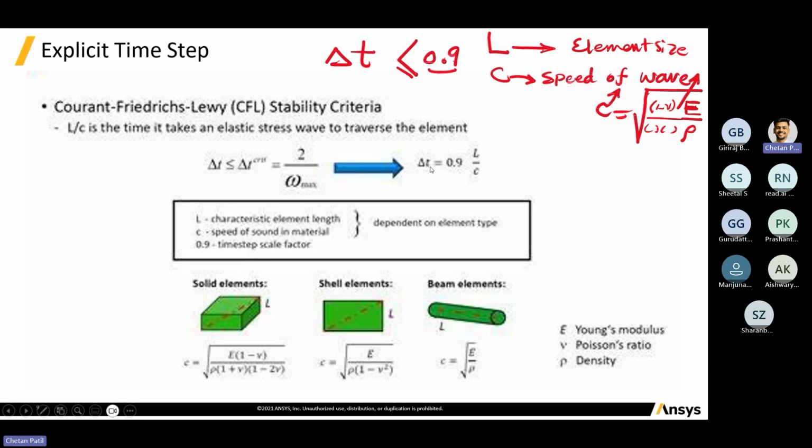Once you get that value for the overall model, you will get a precise idea of where the CFL criteria is satisfied with the least value, and a larger value in the overall model particularly affects the simulation's accuracy. I'll let you know how to find the CFL for any kind of simulation that we are trying to solve. Once this equation is solved, you will have an idea about what amount of computational time is required and what the accuracy of the simulation will be.